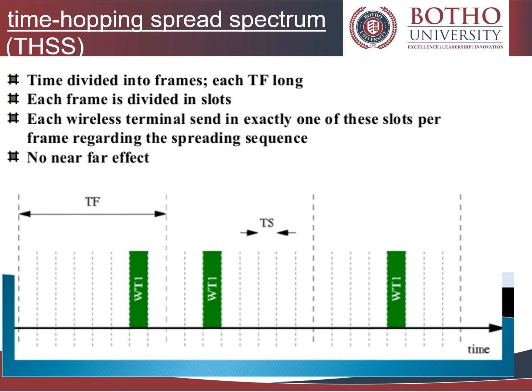To achieve low probability of intercept, which is also called LPI, the transmission time is changed randomly by varying the period and duty cycle of the pulse using a pseudo-random sequence. The transmitted signal will then have intermittent start and stop times.